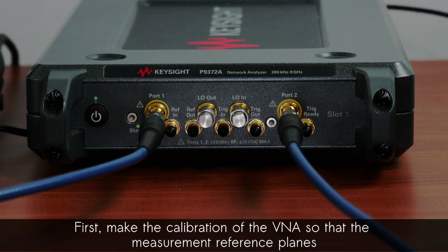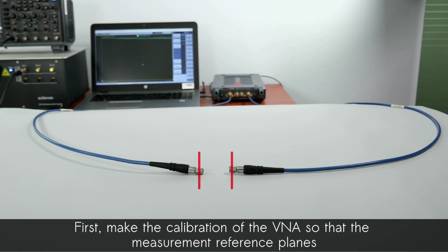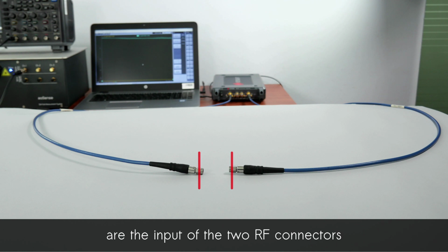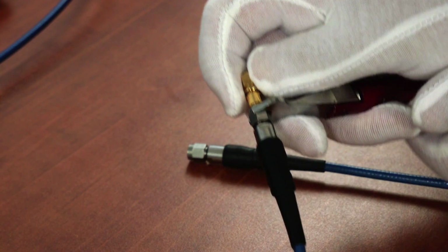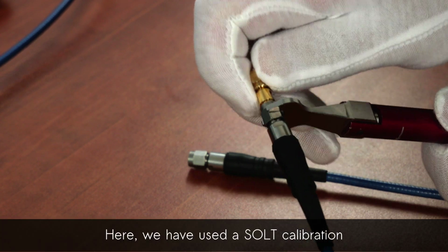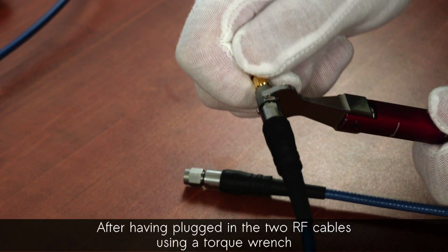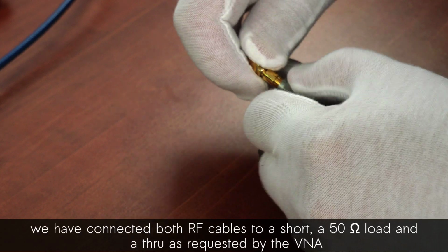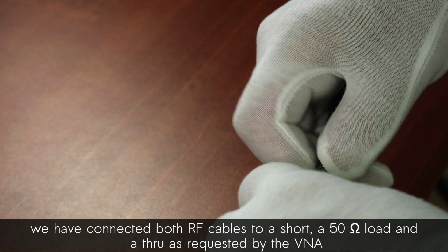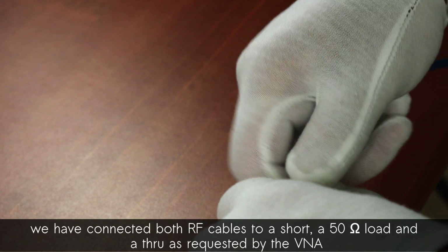First, calibrate the VNA so that the measurement reference planes are the inputs of the 2 RF connectors. Here, we have used a SOLT calibration. After having plugged in the 2 RF cables using a torque wrench, we have connected both RF cables to a short, a 50 ohms load and a through as requested by the VNA.